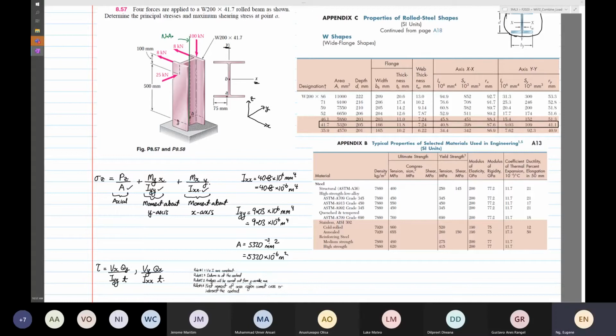So what I've done down there, maybe it's too small on your screen, I've pasted the rules. Rule number 1, V and I are constant. Datum is at the centroid. Analysis is carried out from the Y variable maximum. First moment of area region cannot cross. So these are the rules.